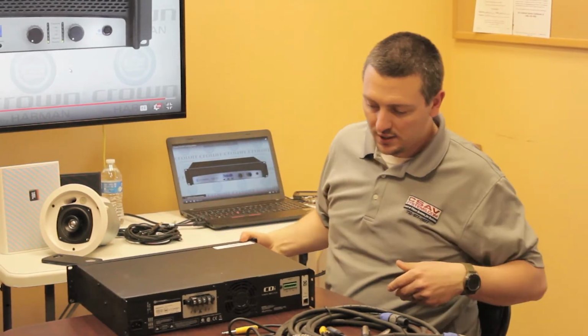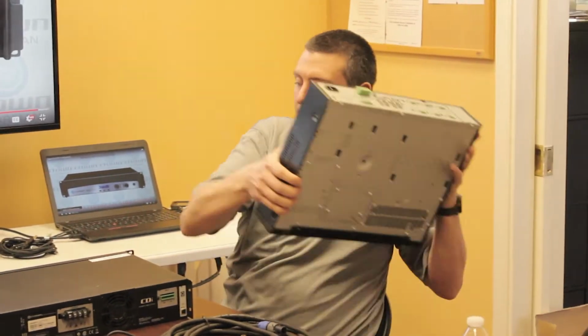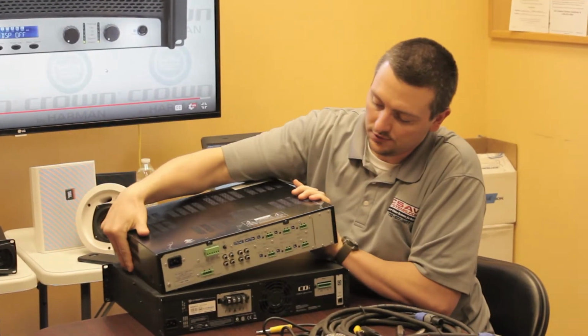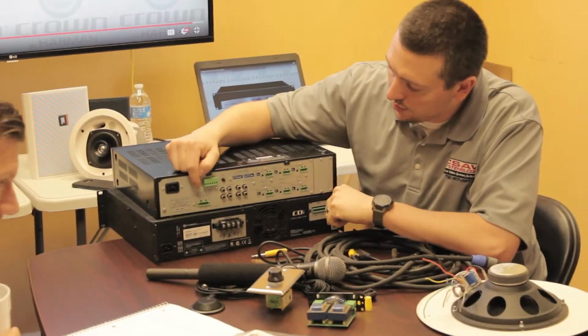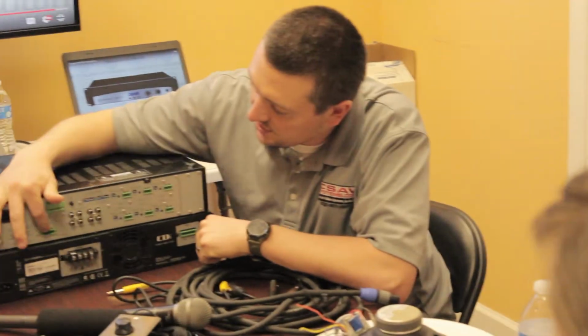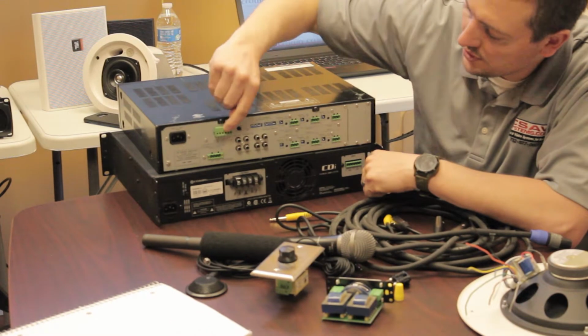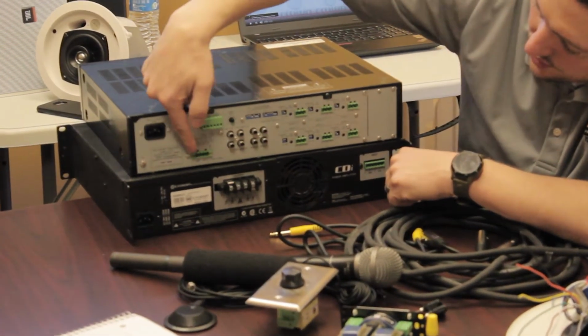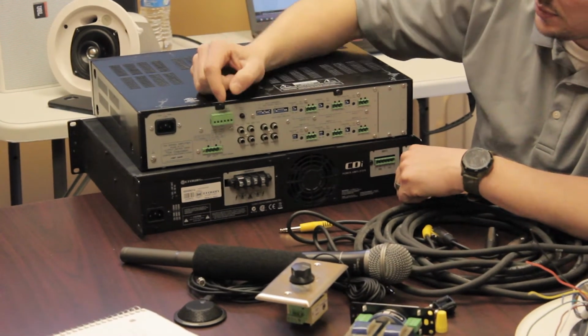All right, so we've got a few different connections for amps and speakers. If we're putting the speaker output on here, we're going to have a Phoenix connector, which is going to look like this, and you put it in wherever it's saying assign. So common, and we're going to go to 70 volt. You screw it down, it locks in place.